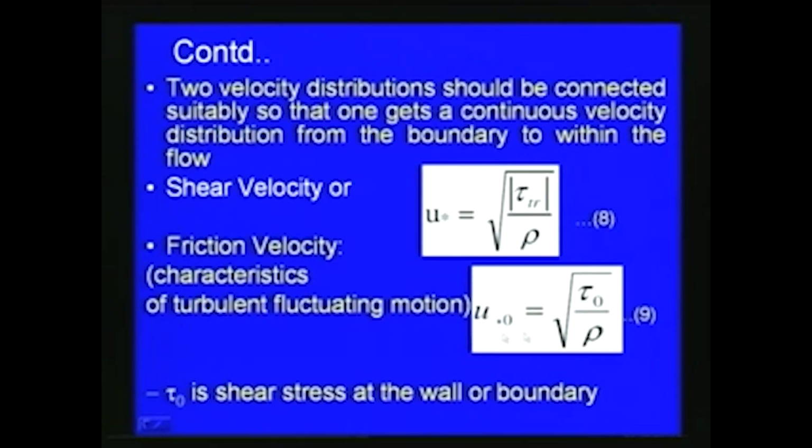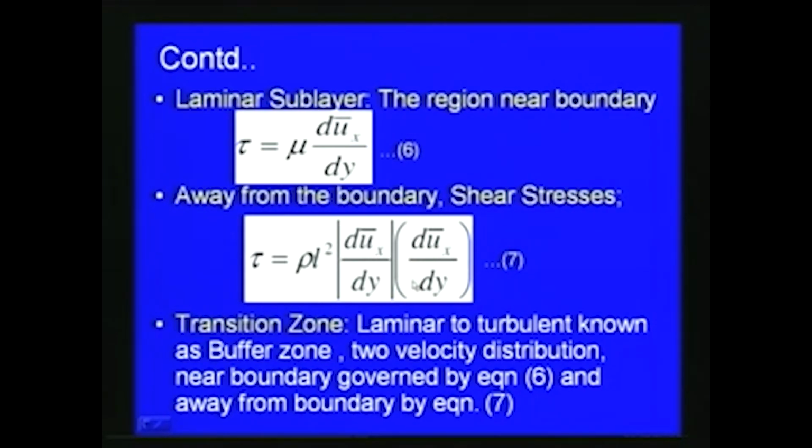So, these various parameters are now defined, and if you know either the mixing length or the shear stress or some of the other parameters, then we can determine the velocity. The zero equation model or Prandtl's mixing length does not directly give a complete solution, but we can use it in combination with some measured values or with some other observations. That is generally this theory.